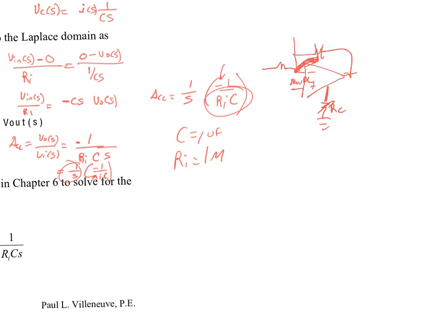So what you need to do is actually put a resistor in parallel with it so all the DC stuff goes through here and all the frequency goes through here. So a real-world integrator basically has this additional R value here, which is going to shunt off that value. And how do you do that again?